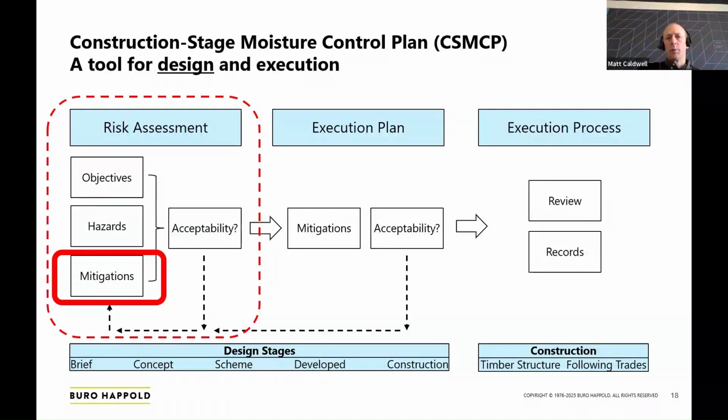If you've got a very large plan area, can you go all the way up to roof, enclose it before you move horizontally? What temporary protections could we use? Self-adhesive membranes, or potentially a temporary enclosure. Or if the mitigations are limited, then maybe we need to change the way that the roof is structured, and the materials, and what have you.